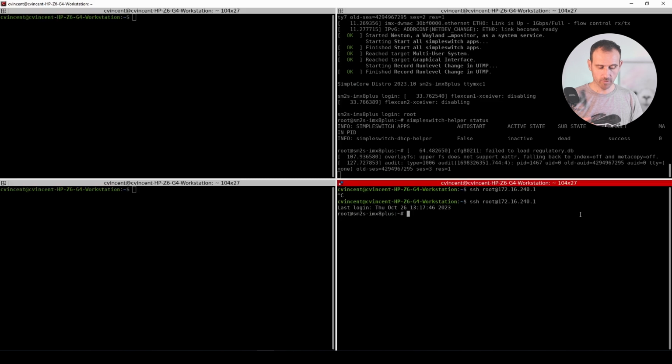Of course, you can start the DHCP container helper from the command line as well. It's just in case you don't have our cable kit, a null modem cable and a USB to RS232 adapter, that you can do that instead. Both ways will start the DHCP server directly on the board and allocate an IP address for the board on your computer. So we have a connection between the board and your computer.